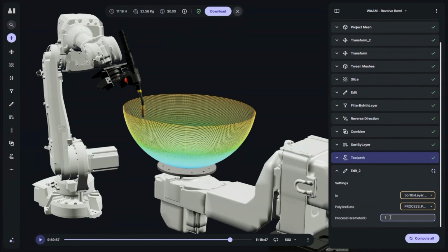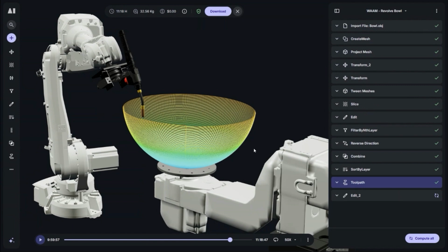As long as it's something that you can call in the toolpath, we can refer to it here. For wire arc, it's often the case that, say, on your first layer, you're using one set of welding parameters. On your following layers, you use another set of welding parameters. On weaves that connect to other weaves, at the end of that weave, you need a different welding parameter. So we can isolate all these different regions, filter them out, and give them their different job IDs or welding parameters or whatever we need to call. And it will, in the toolpath during printing, call that and make that change.